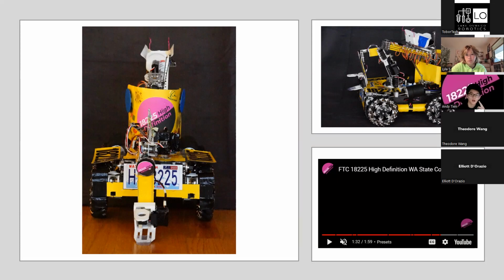And the question was, what do you use for wire management? So we basically ran a closed coat hanger system on our retraction string. If you look to the top right, there's a bunch of little loops of wire, and as that string extends, the wire would naturally extend itself to come with it. And as the string retracted, the wires would naturally fall back into their place designated by the little coat hangers.